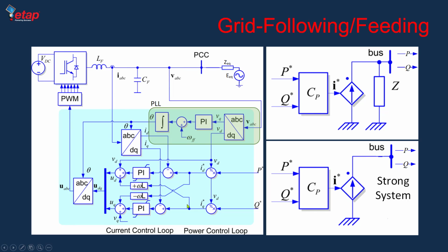Now, when it comes to this controller, we're controlling the current, but keep in mind the inverter at the end is putting out a DC voltage that, after filtering, becomes AC. So there is a voltage drop across this reactor. That voltage drop, which is jωL, in time domain gets compensated here to determine the voltage behind this inductor. So this UD and UQ are the voltage behind this inductor that is fed to the PWM to determine basically the switching commands for the pulses, okay?